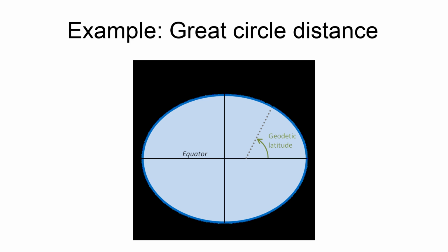Delta sigma is the angular difference, and thus the great circle distance is achieved by multiplying with the Earth radius. This expression also works at the poles and at the plus or minus 180-degree meridian. Note that arctan must be replaced by atan2 in computer program implementation. There are several other examples where the use of vector algebra simplifies standard problems. For a general comparison of the various representations, see the horizontal position representations page.